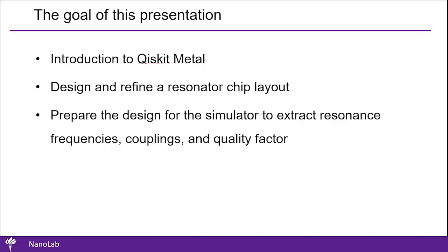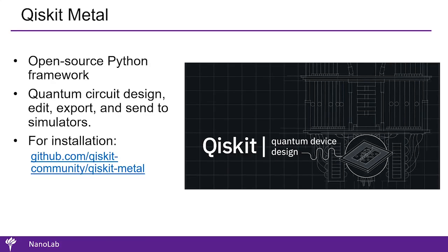We begin by introducing the Qiskit Metal library, setting up a design, and in the end, a step-by-step guide to create resonators, launchpads, and connections. In the next session, we will connect these design steps to electromagnetic simulation using ANSYS HFSS to perform eigenmode and impedance scatter simulations to determine the modes of resonance frequency and find the scatter parameters of our microwave chip. Also, you will learn how to export the design in GDS to proceed with fabrication steps.